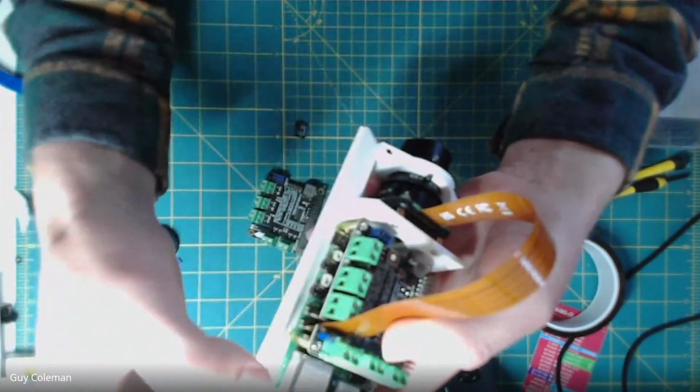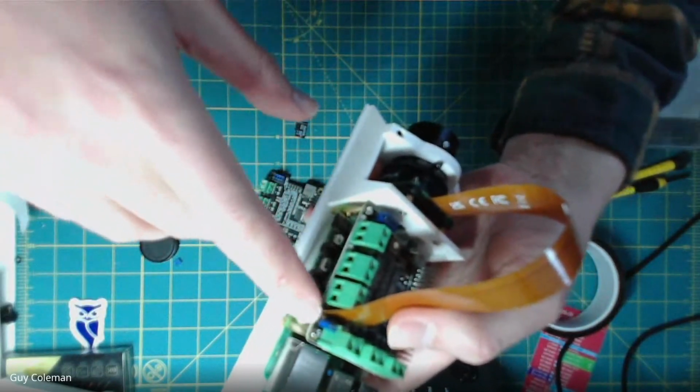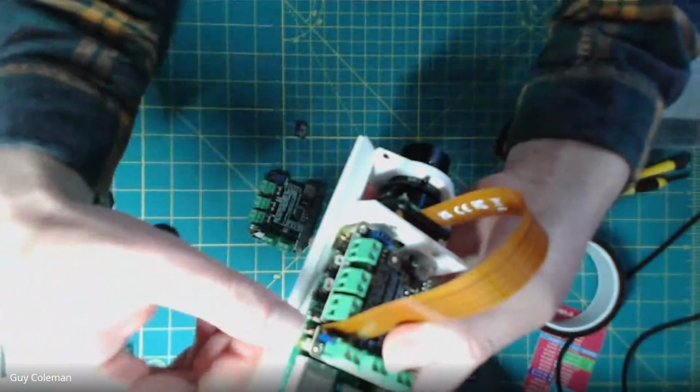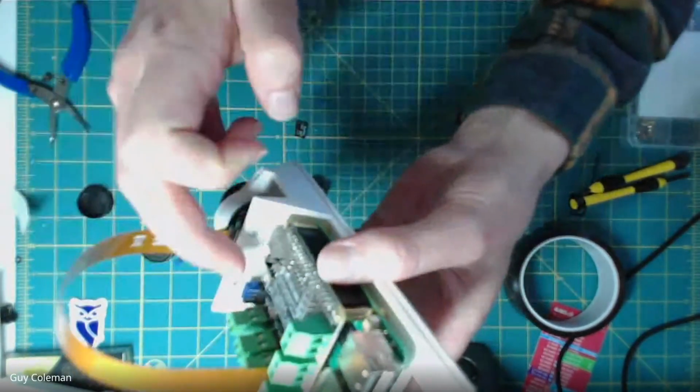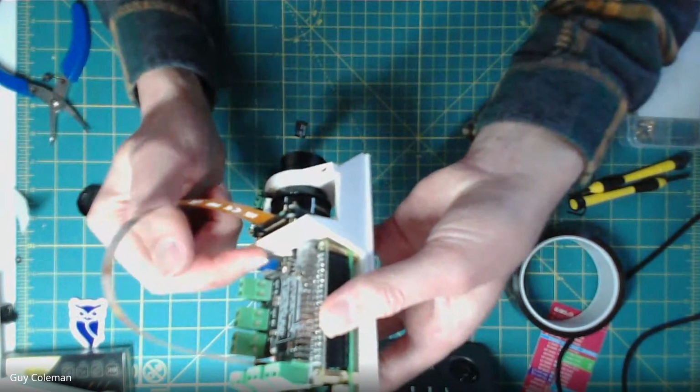But if you don't want to use that, just make sure you have that pin across. A red light will shine when all the outputs are enabled. So if you're having a couple of issues, maybe getting it started, there might be the power pin. Make sure you double check that. If the outputs aren't running, maybe check all these pins here are correct.